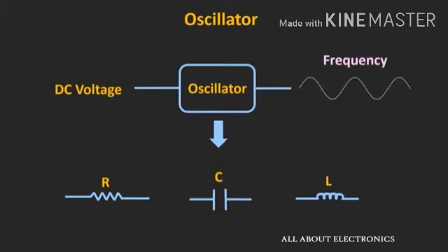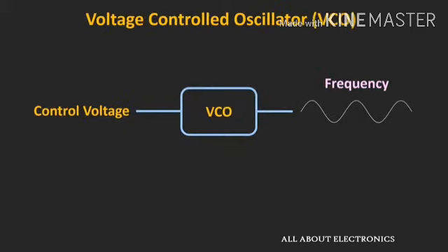frequency. So in the conventional oscillator, if we want to change the frequency, then we need either a variable resistor or a variable capacitor, and manually we need to tune these components to change the frequency. This voltage control oscillator also needs these passive components for the frequency generation, but with the given set of passive components, just by changing the control voltage or the tuning voltage, it is possible to change the oscillation frequency. So we can say that voltage control oscillators are much easier to tune compared to conventional oscillators.